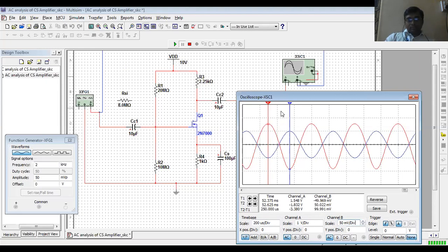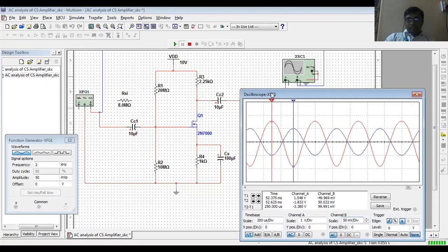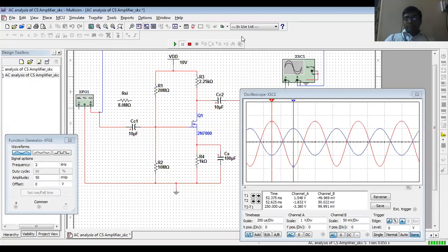This is the signal that we are going to calculate here. Now you can put this value in your observation table. We will later show you all the values at once. Now this is the first, this is called the V naught. After calculating this V naught, that is nearly 3.4 volt, you can observe that it is nearly 34 times, so the gain is very high.